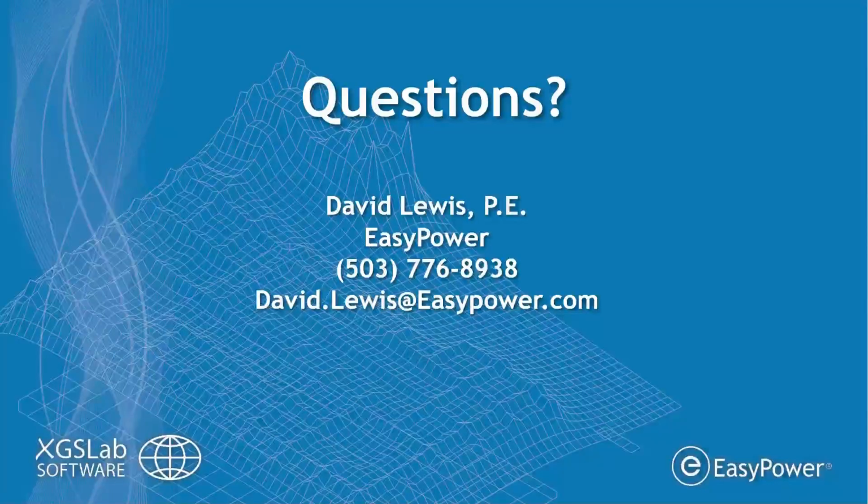Going through the webinar, we had a couple of questions about ground potential rise and the relationship to safety and limitations of ground potential rise. When we're looking at touch and step voltage potentials, we're looking at the difference of a system from one point to another, whether that's between an individual's feet and their stride length, or between an individual's hand and their feet.